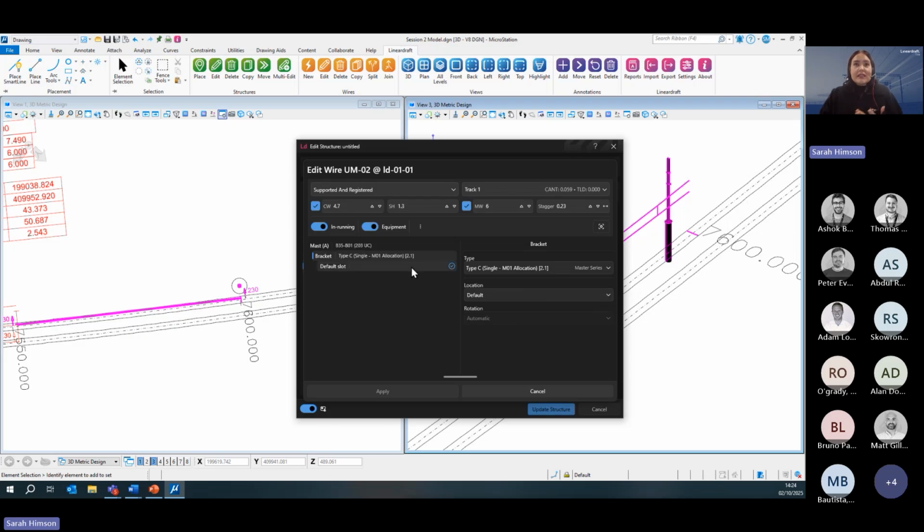Moving on then, you'll see a default slot has become available. And this is where we'll choose the wire support. So you can see immediately my preview has updated. We've got a wire support on there, and that's simply showing me whatever was top in this list for wire supports. So I can choose the type. And then I can go ahead and choose the style, so pull off or push off.